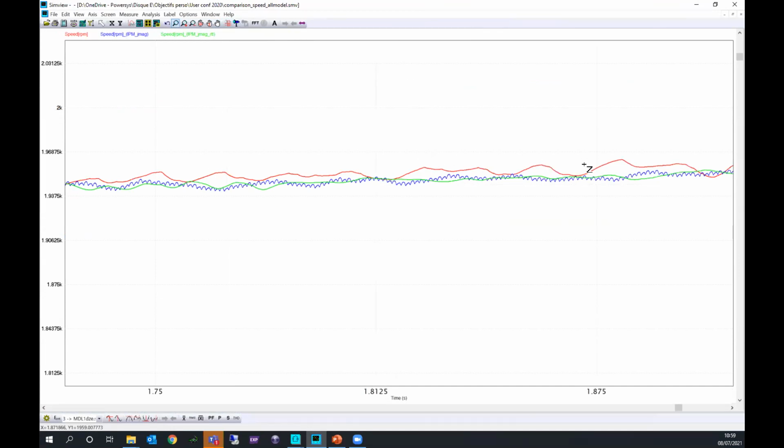the shape is quite close, but if you prefer and if you want to get your real behavior, you need to use Gmag, as I told you, because here you have some ripple for Gmag, and this is a real behavior of your motor. And Gmag RT has the same shape as Gmag Designer, but the shape, I mean, will be more linearized.